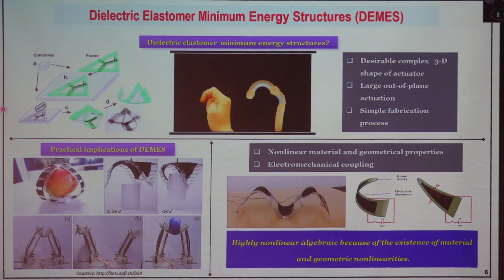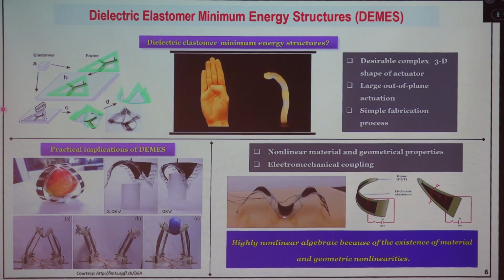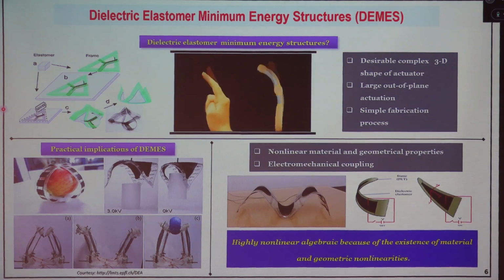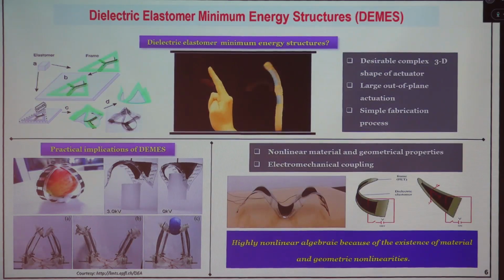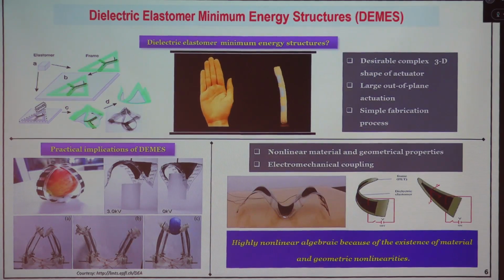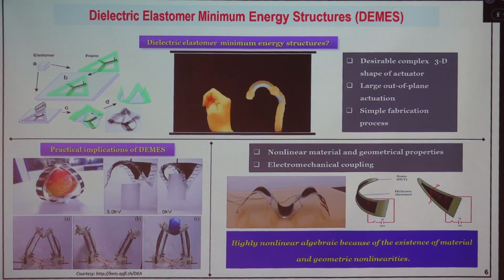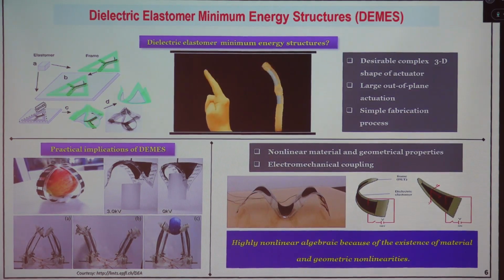Now we initially provide pre-stretching to that membrane, so already that membrane is compressed in the thickness direction and expanded in the areal direction. Now for the low voltage, if you have already pre-stretched that membrane, whatever response you want, you will get at low voltage. If you are not pre-stretching, you have to apply a higher voltage.